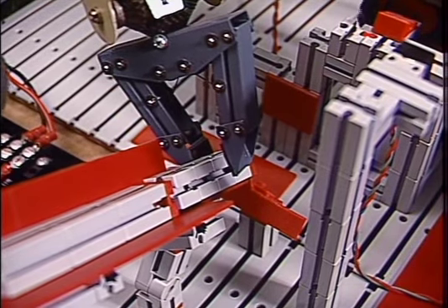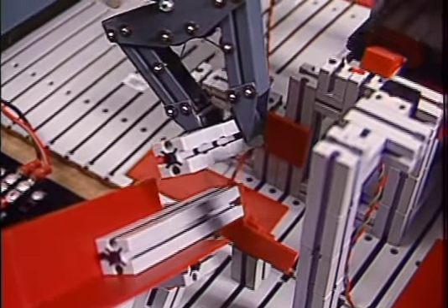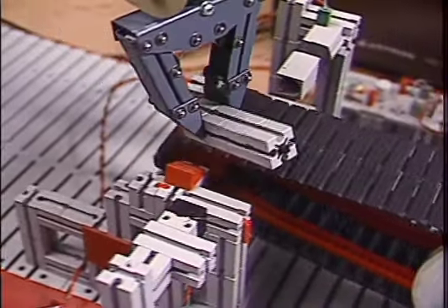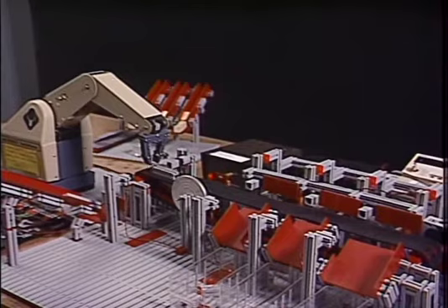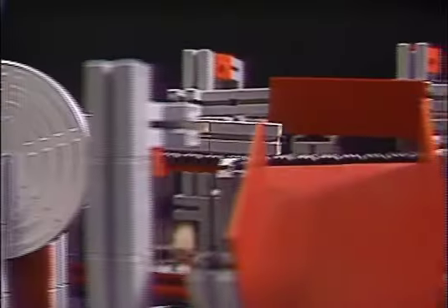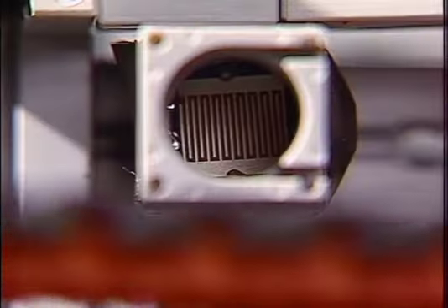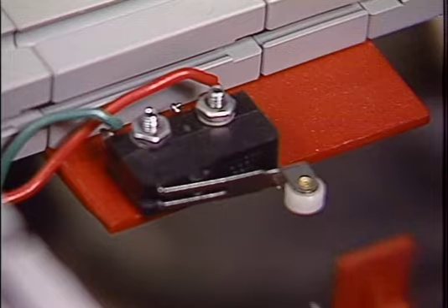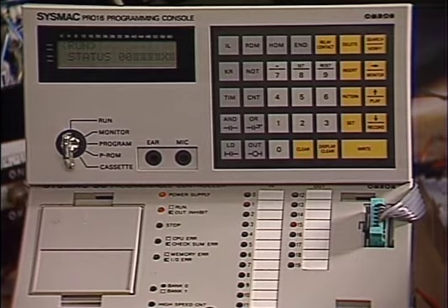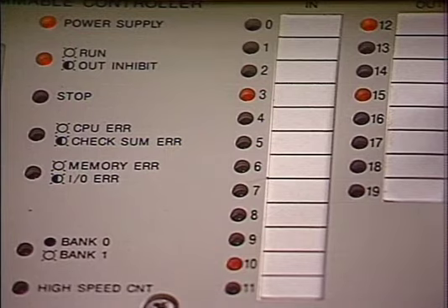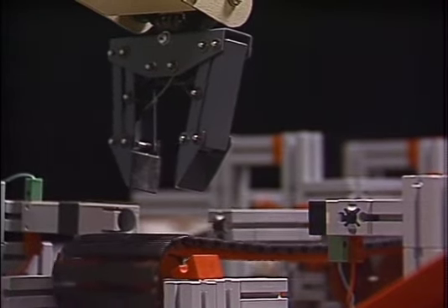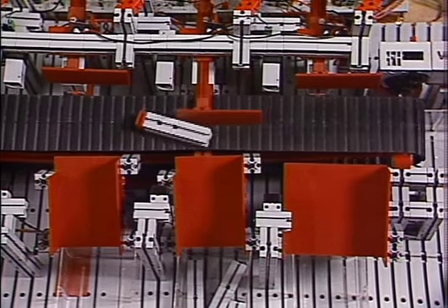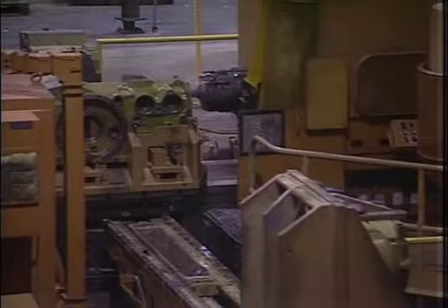A scale model of a sorting conveyor has been constructed in the laboratory. Parts are loaded on the conveyor by a robot from a gravity-fed chute. As the parts travel on the conveyor, they pass in front of several light-sensitive detectors. When the part interrupts a light beam aimed at the detector, an electronic signal is generated, amplified, and processed by a programmable controller. The length of the part is determined by the amount of time the beam of light is interrupted. The controller then decides at which of the three chutes the part will be ejected.